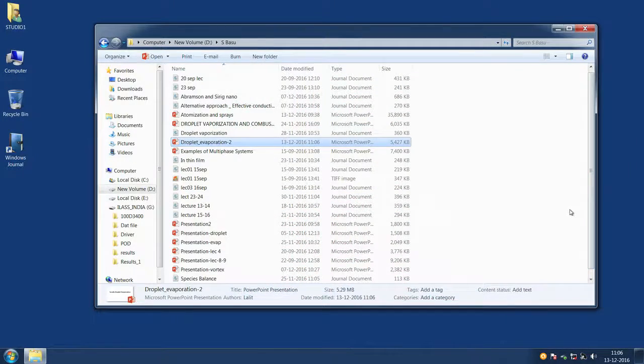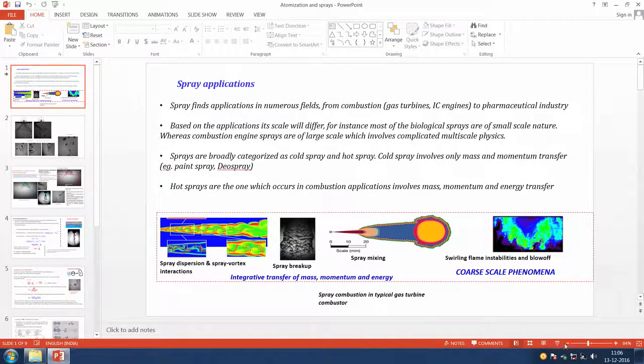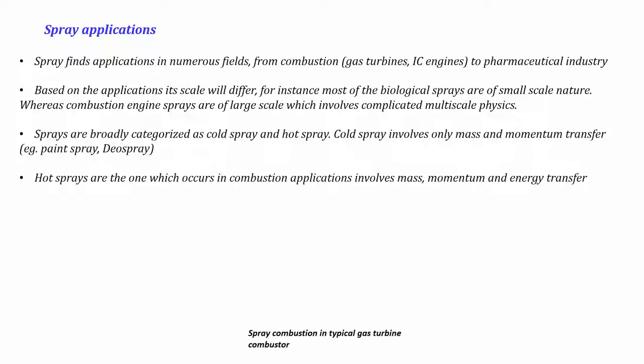Now we are going to start one of the important topics in the case of droplets, and look at how their shapes actually change. So this was all evaporation and flow where we assumed that the droplet shape does not change drastically. It is just the shape change that happens due to evaporation. For example, in sessile droplets it either comes down in CCR or CCA mode; there is no corrugation of the interface, and there is no breakup of the droplet.